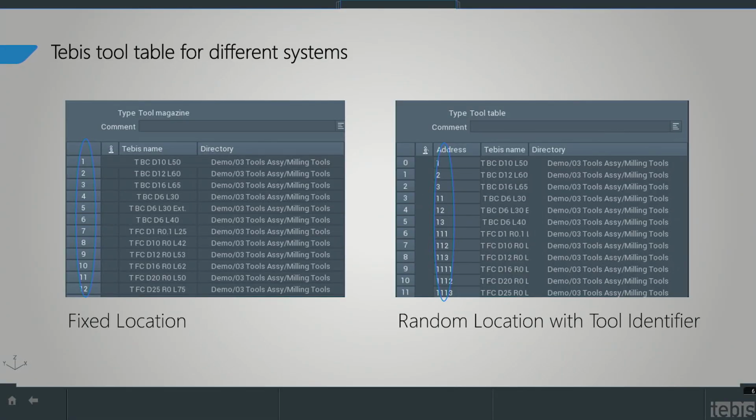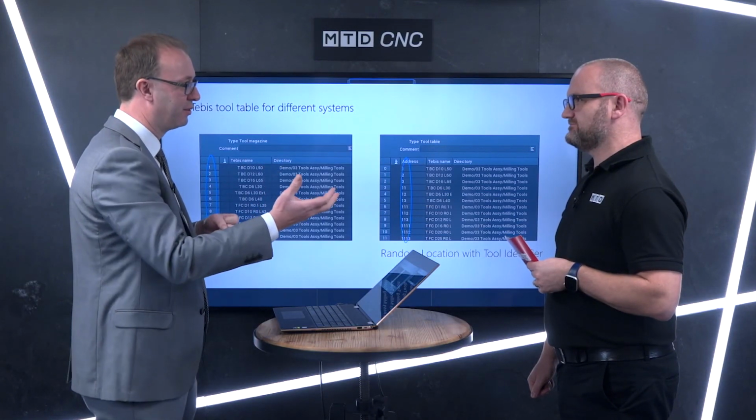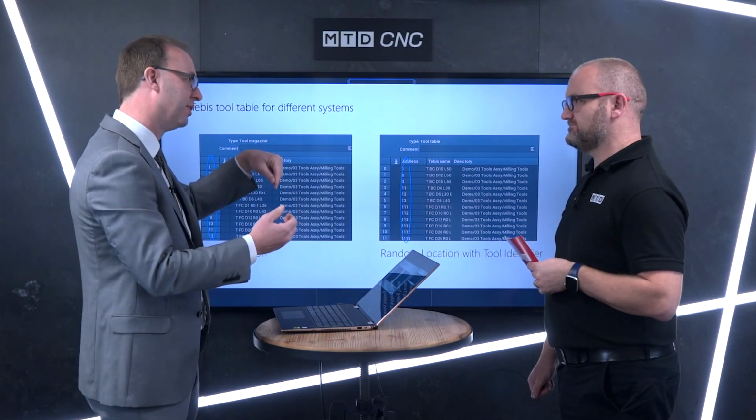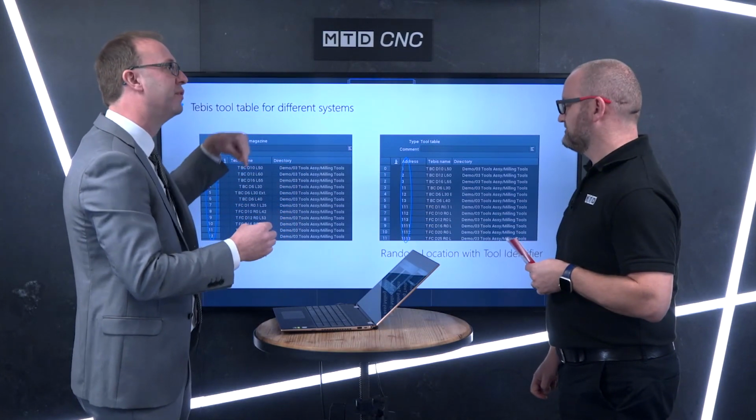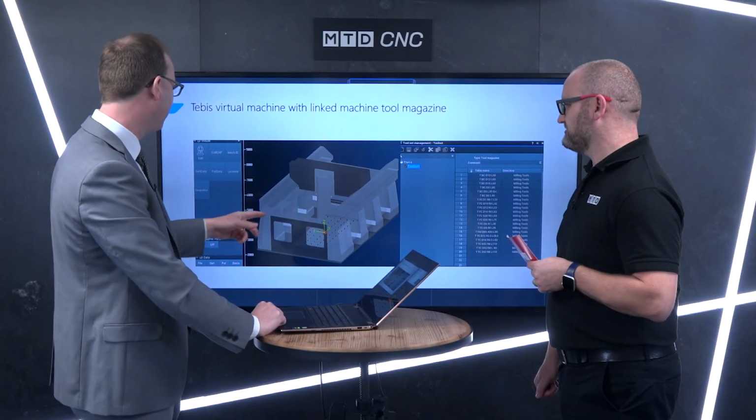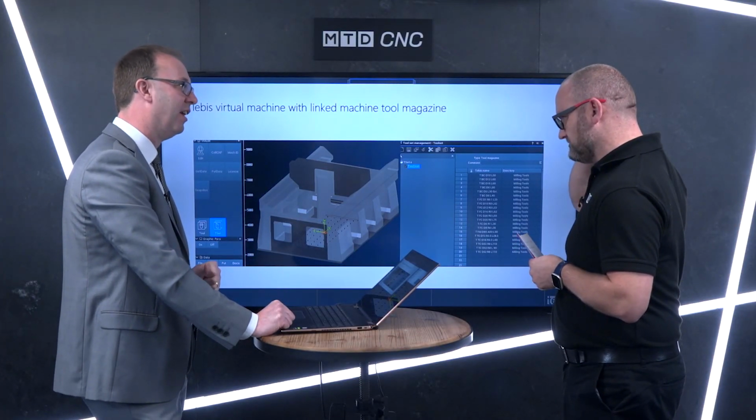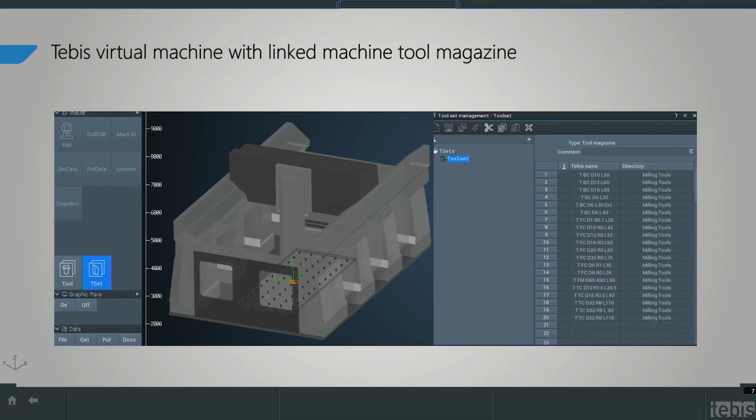Now all of this is possible because of all of the automation in the system and how it links in. But it's very important for managing the machines. And you can even mix and match. So you can have your tool magazine running on the machine for a lot of your standard tools, but the machine can automatically then move to a manual tool for something that's special, and the system defines all of this. And these again can be attached directly to a virtual machine that's in our libraries structure. So when you select a machine to program with, the tool set is automatically applied into this environment.